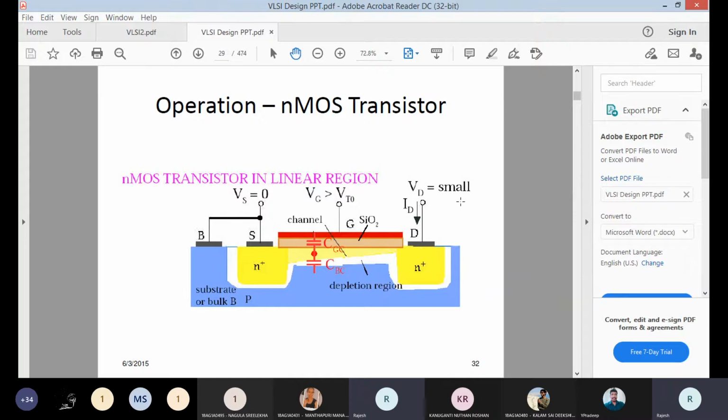If VDS is less voltage, few electrons will move. If VDS is more, more electrons will move. So IDS is directly proportional to VDS. As you increase VDS, current IDS will also increase. IDS represents drain current, drain to source current, which is represented as a hole current. But our conceptual view is electrons are moving from source to drain. In reverse, holes are moving from drain to source.